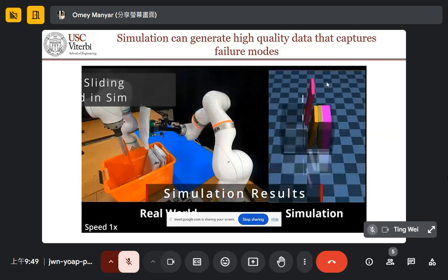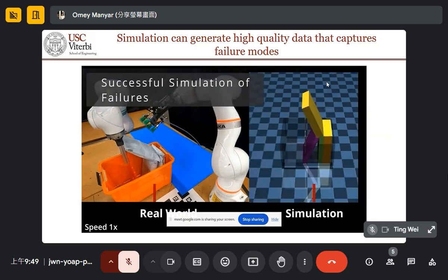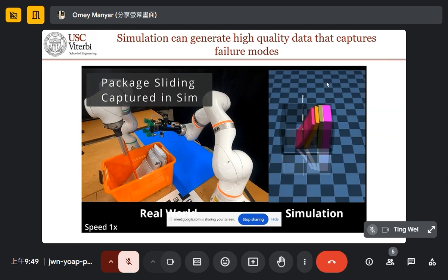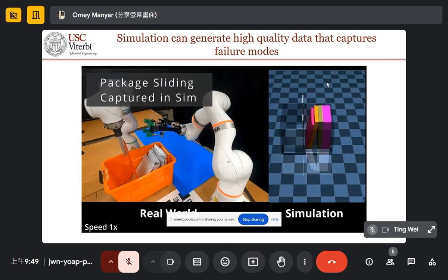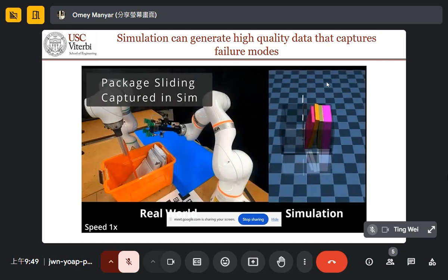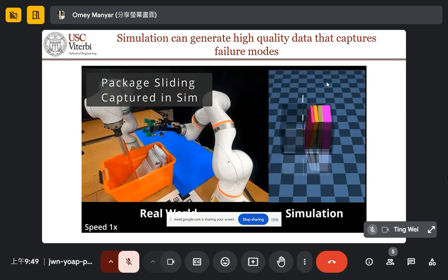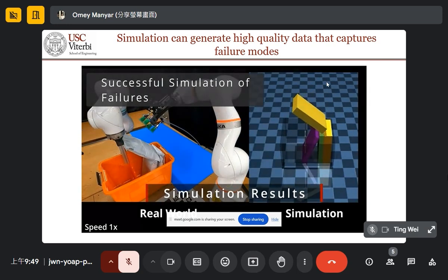And in addition to that, we use deformable object simulation in MuJoCo. One thing is that when you're using simulators, there's always a sim-to-real gap. What we found is that rather than just doing simple domain randomization and adaptation, we can simulate failure modes and then use that failure mode data to do some sort of contrastive learning, where the robot learns a policy which understands what actions not to take.